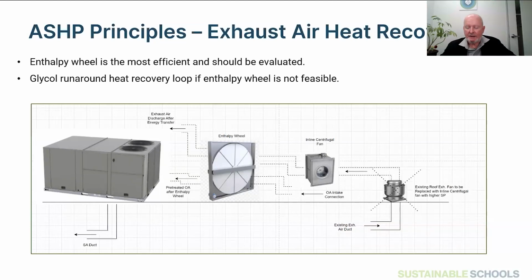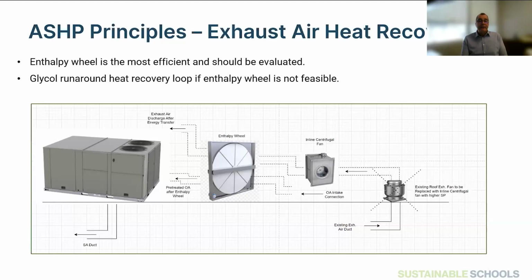And your building envelope standards are higher for new schools now than they were even 25 years ago, right? I think they're higher even than they were 5 years ago. We've upgraded our windows. We've added more insulation to the slab. We have exterior insulation now behind the sidings and the brick. So yes, the roof insulation has been increased. So the envelope is much more robust.